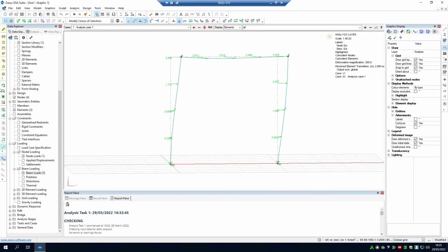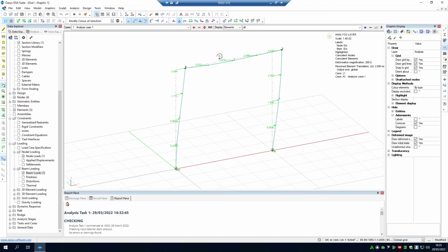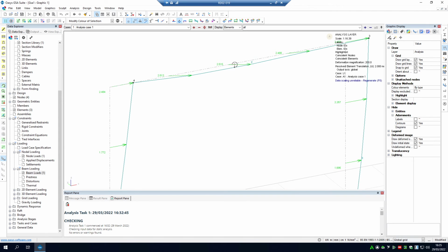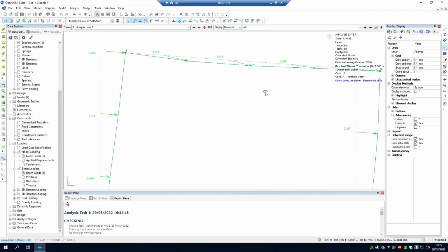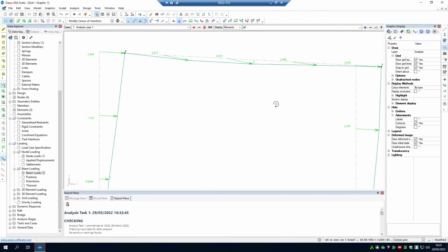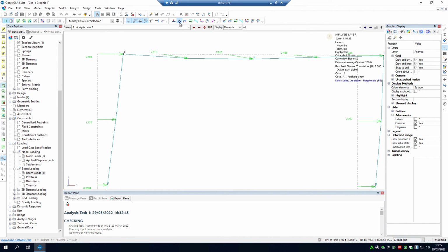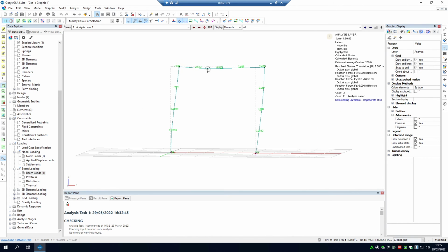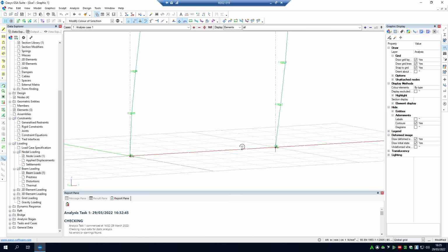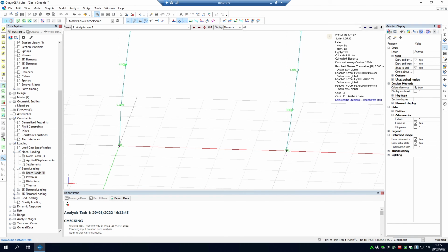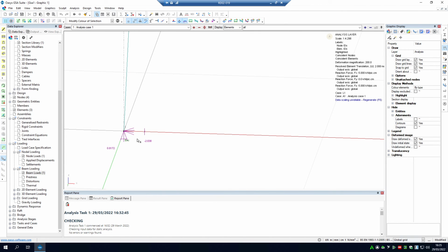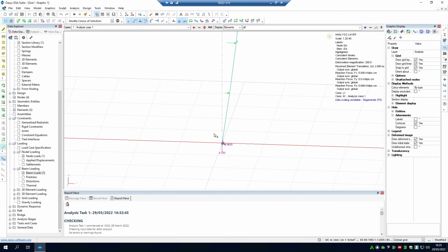We can now see, go back onto rotate. This is exactly how much deflection this structure is undergoing right now. And that's through the displacement diagram. Then you can add the reaction diagram, which will give you a reaction force here. Again, we annotate this, it gets rid of them, but shows us exactly how much of a force is being applied to our points.